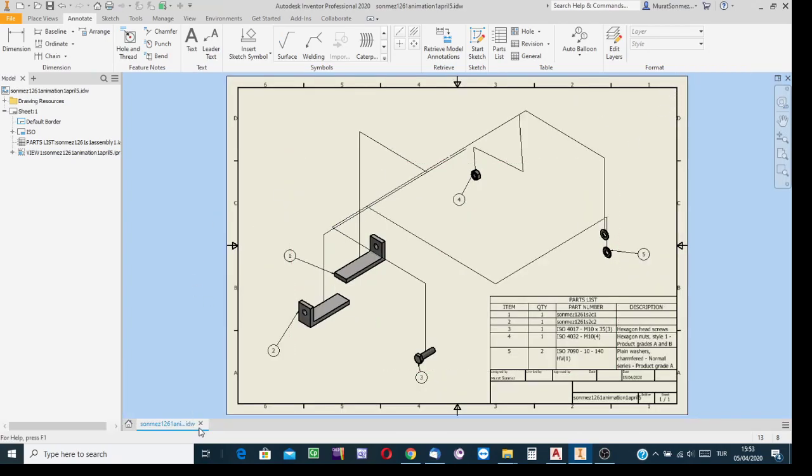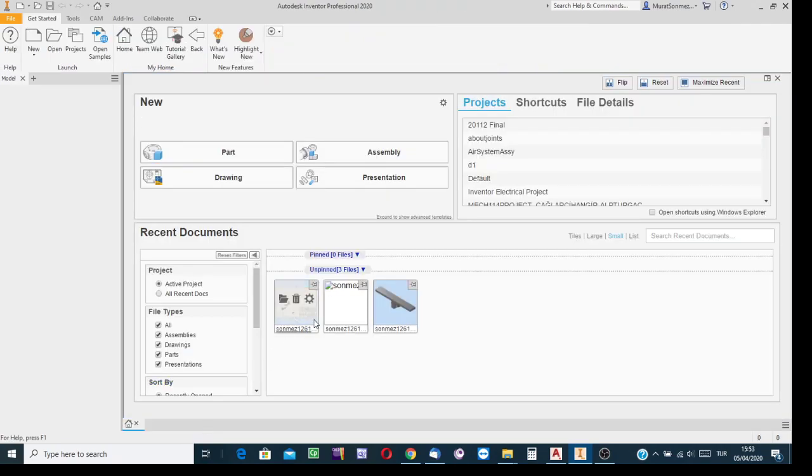And the data files at the background: while we are creating the presentation file, sure, Inventor created some other data files at the background. So, well, collect all the data files created by the software, and also, to collect the newly created files, apply one more time the pack and go process.